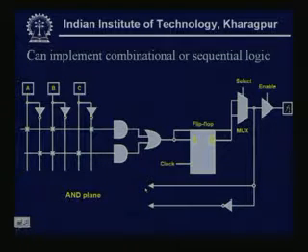Now, some more advantage is also there for this fixed OR gate or plane. See, earlier it was only combinational. Now, we can realize the sequential logic also by using a PAL structure. As this output plane, normally OR plane we call the output plane because the output function is computed or taken from the OR plane.